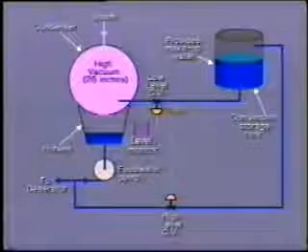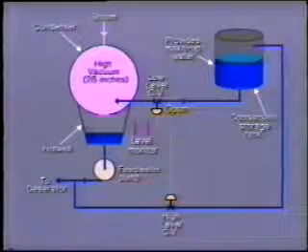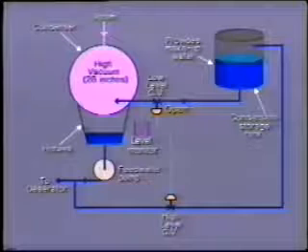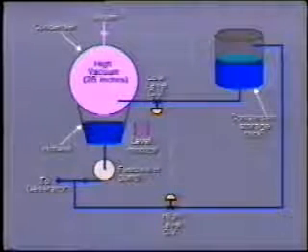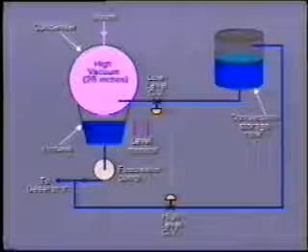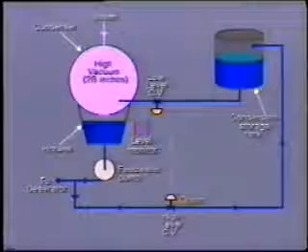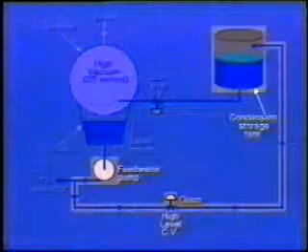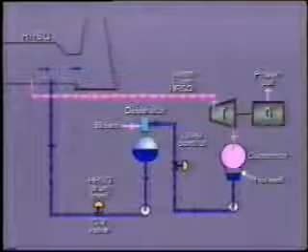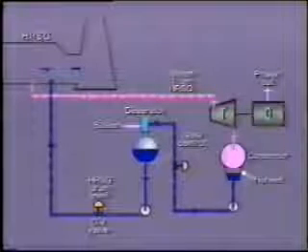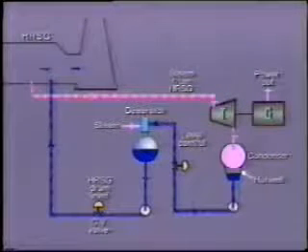When the control valve opens, water flows from the condensate storage tank into the hot well. The reverse will happen if the hot well level starts to rise. In this case, condensate from the discharge side of the condensate pump will be sent back to the condensate storage tank. So in this system, we have continuous circulation of steam, condensate, and feed water round and round the system, with only minor fluctuations in levels of the hot well, de-aerator storage tank, and boiler drums.